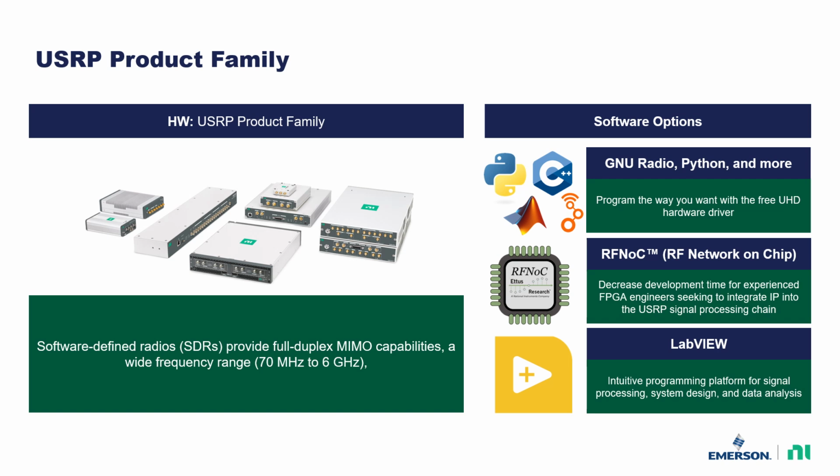In addition to working with popular open source software, we also have software that was developed by our team called RF-NOC, or RF Network on Chip, that's meant to abstract away the difficulties of programming the FPGA. We know that not everyone knows how to program using Verilog and HDL coding, and it can be very challenging. So RF-NOC is a tool that's meant to make this easier and more approachable for the average user. And finally, we have LabVIEW support for the majority of our portfolio.